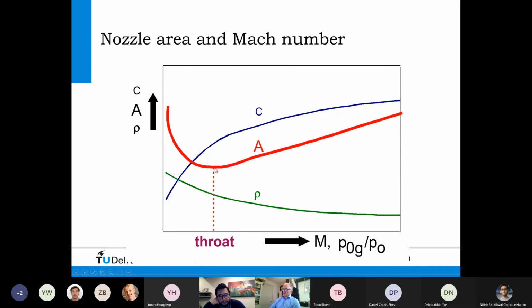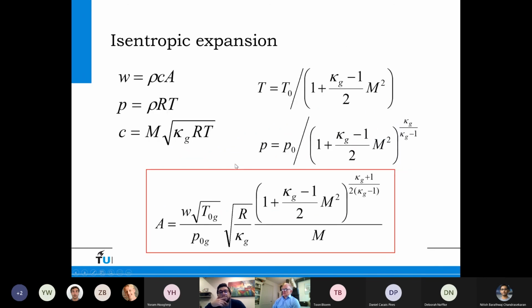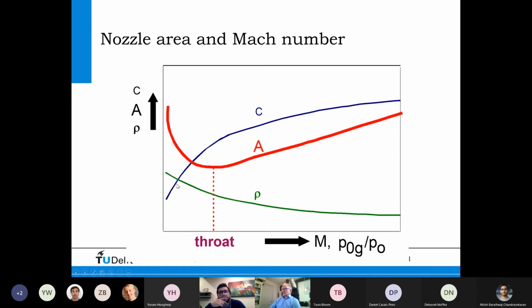So this is the narrowest section, and here the nozzle starts. So this is A. We calculate A using this relationship. And then this is the velocity. This is sonic velocity. The Mach number here is 1. And here it increases because we assume that there will be no shocks and no non-isentropic phenomena.